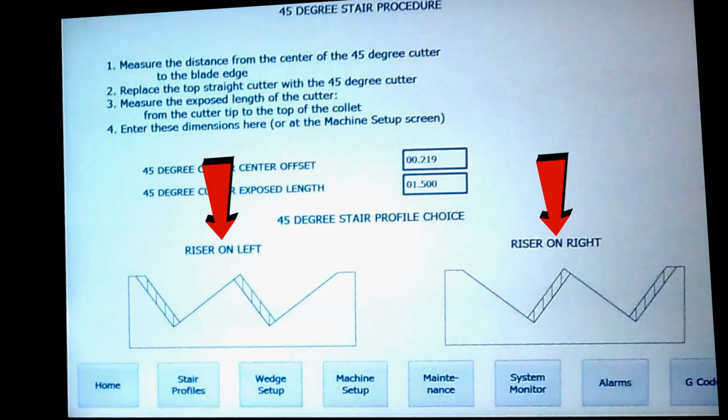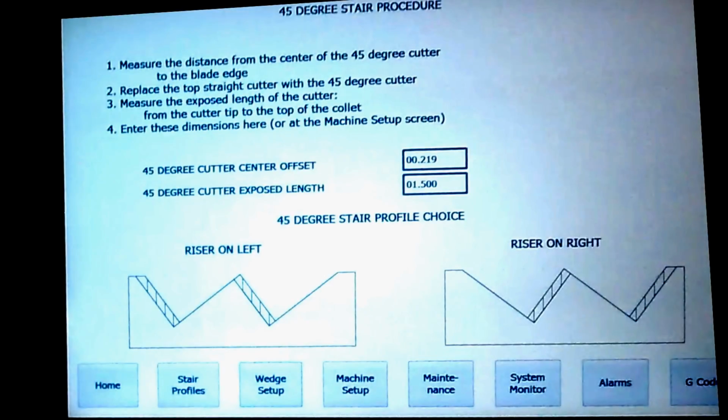These two give you landing cuts, and yes, the landing cut will have a 45 cut on the riser. That way your first riser is also a riser with the ability to mount it so that you can't see the end grain.